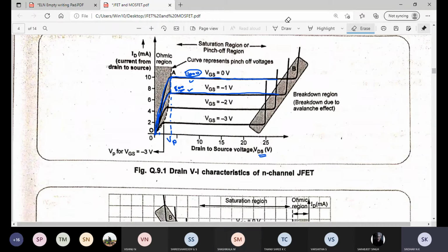If you say yes, I'll move on to the third step. Any doubt here? How has this saturation come down? Because the channel size decreased. If the channel size decreased, the number of electrons in the channel also decreases. Fewer electrons means the saturation also falls down. That's why we get lesser saturation for a more negative voltage applied to the gate. Understood? Yes, sir. Right, thank you.